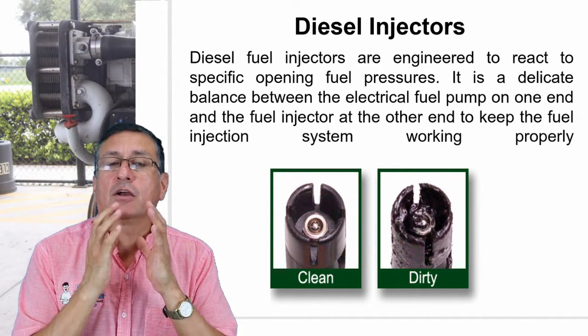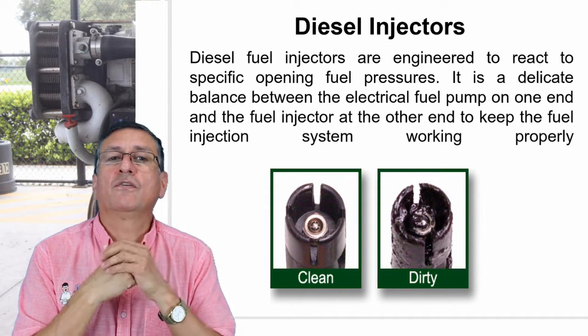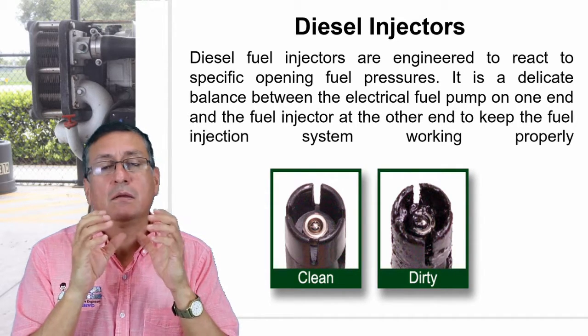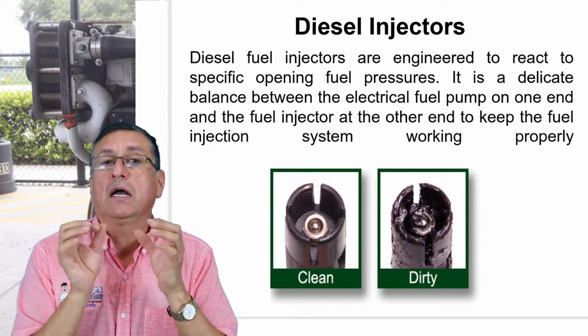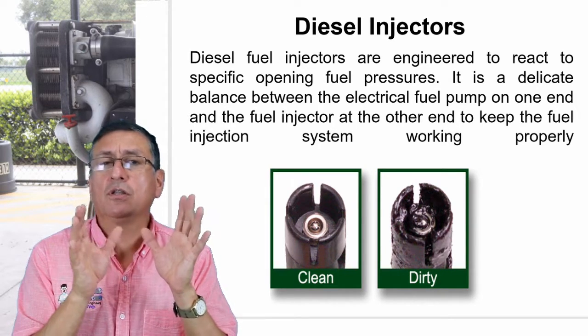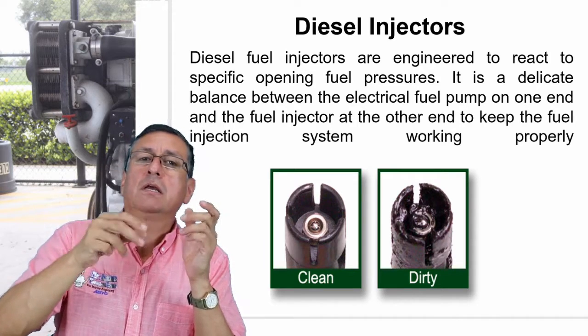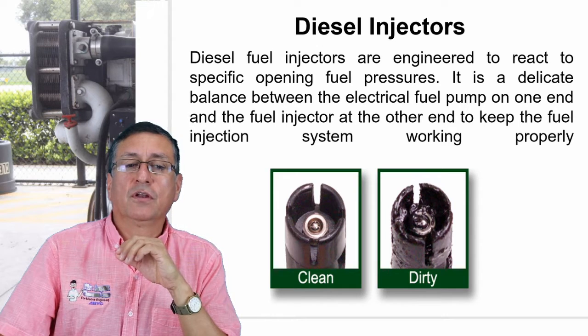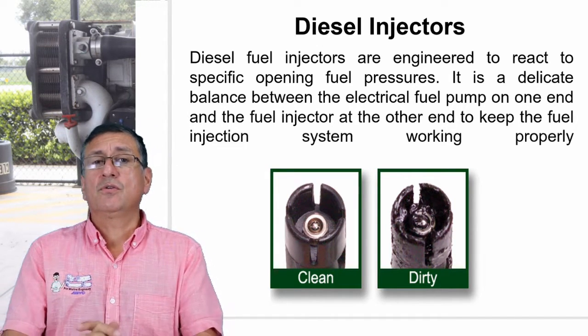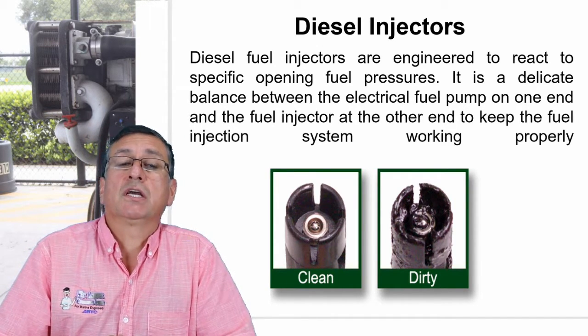The recommendation is to keep the nozzles of the injectors clean. When you remove the head, you can remove the injectors and send them to the machine shop, or if not, you can remove the injectors periodically, clean the nozzles and verify the condition of the nozzles. In what situation do you need to remove the injectors? Normally when you check the compression.